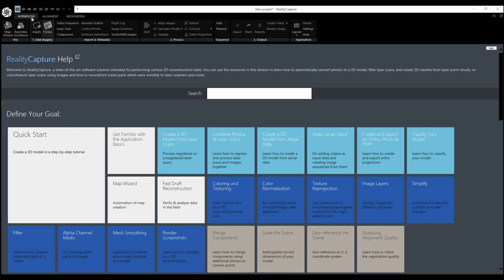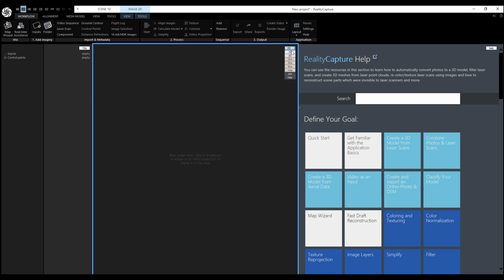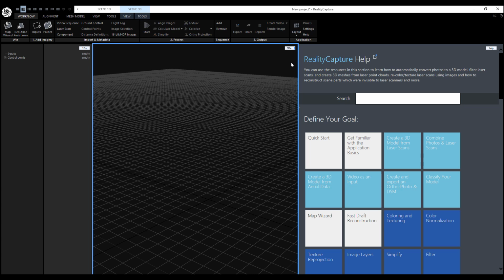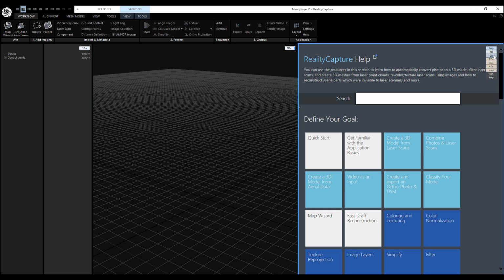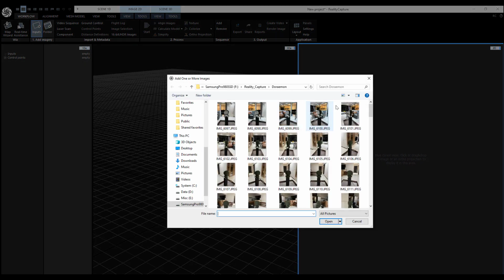To display the contents list and the working area, change the layout from single view to a 3-panel view. You can also change the view type by clicking and holding the left mouse button on the Aspect button in the top right-hand corner of a view window, then releasing it over the view type you want to use. In this case, I changed mine to display the 3D view in the center and the 2D view on the right.